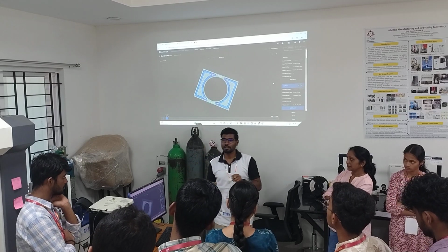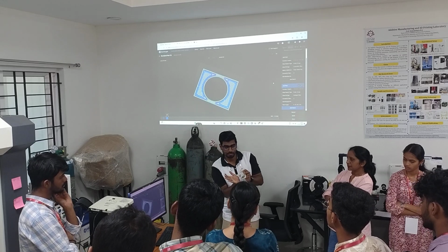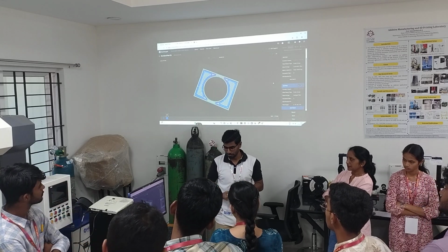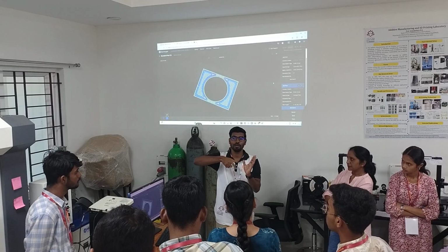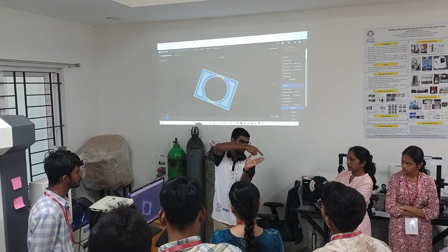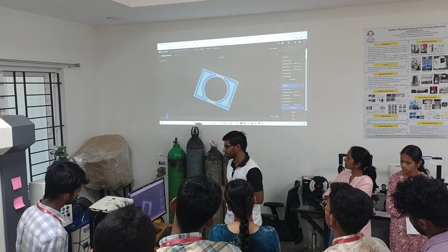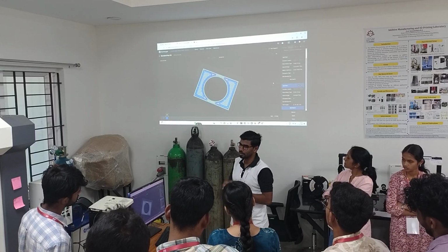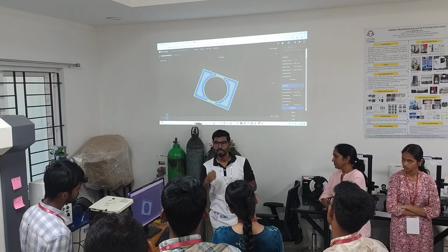So this is one of the disadvantages of additive manufacturing of composite fiber, specifically in this machine, that if you have any curved path, just like a glass or something, it will not be possible to have it along the walls. Even if you place it like this, only some of the layers will have it, and then it will not be continuous along. So additive manufacturing of composite is still in progress and people are trying. But the same thing can be done with a very small amount at the layer level.